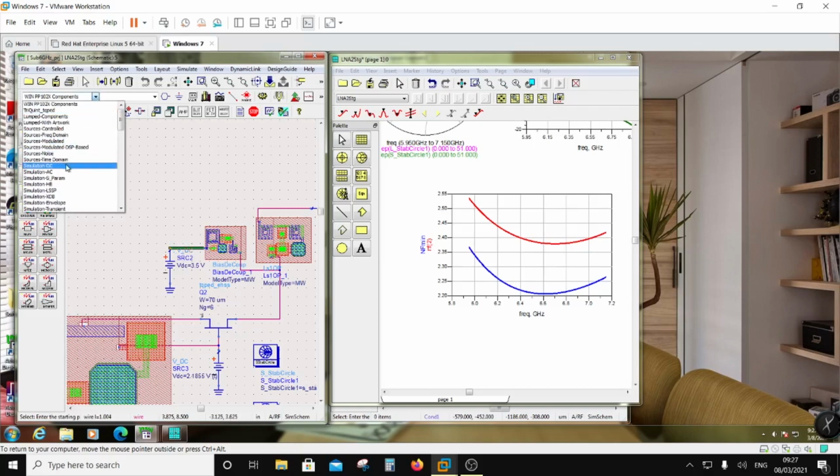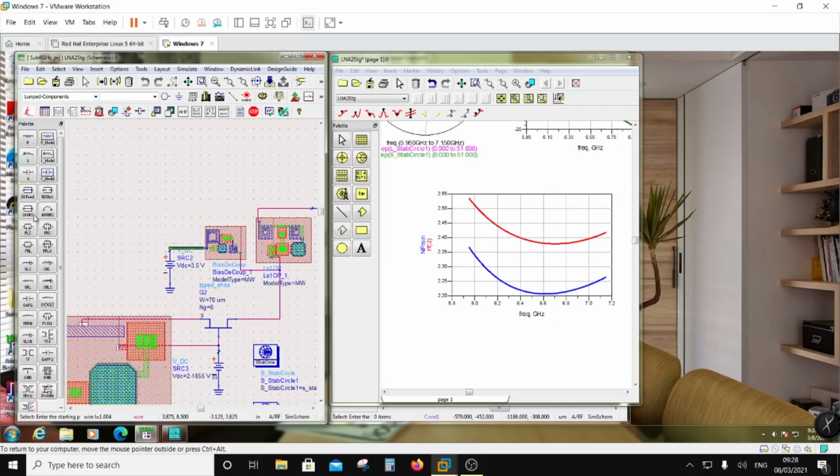So right now it is an AC short here. Now if I replace this by an AC open, which a DC feed does, then the performance should not change a lot. So that way you are insensitive to what you connect for a DC supply.